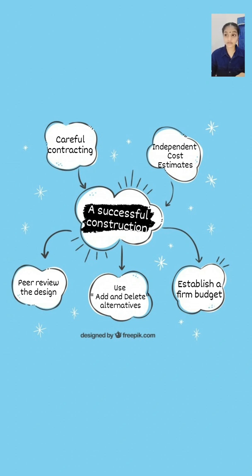Construction disputes are best avoided through a fair allocation of project risk. The guiding principles are that risk should be allocated first to the party who has direct control over the portion of the construction that creates the risk, and when no party has direct control, to the party who is best able to protect against an unexpected loss. When no party has any control, risk is allocated to the owner, who is the party that initiates the construction project and is the ultimate beneficiary of the result.